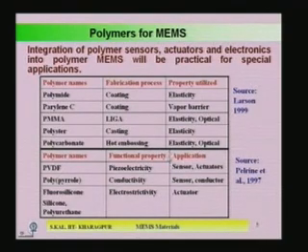So, when you use polymer as a functional material, then we use some functional properties, and those functional properties are piezoelectricity, conductivity, and electrostaticity. Its main applications are either sensors or actuators, and the polymers used for sensors and actuators employing the functional properties are PVDF, polypyrrole, fluorosilicone, and polyurethane. These are the polymer materials which are being used nowadays in different kinds of microsensors.